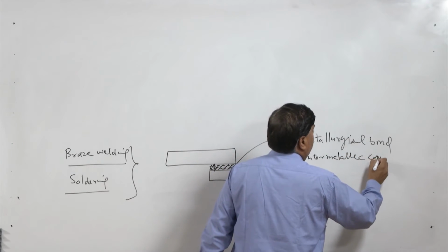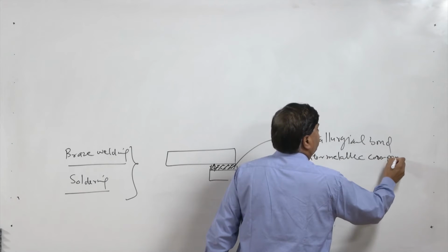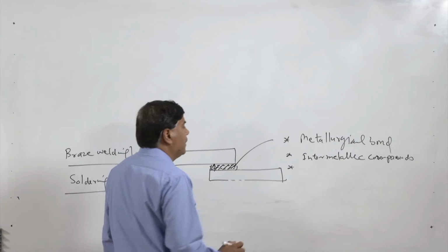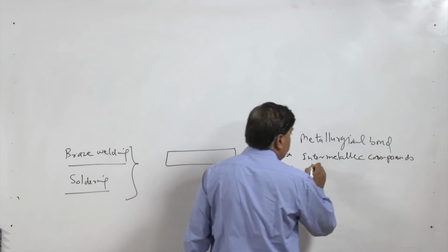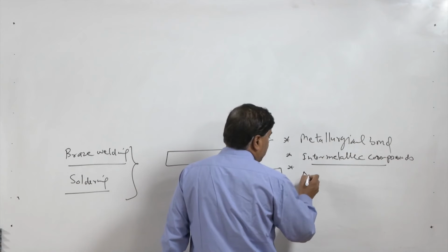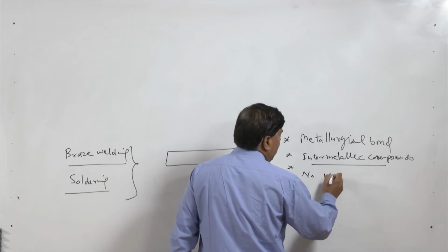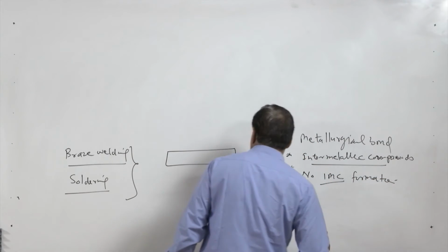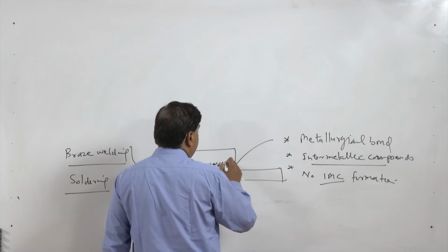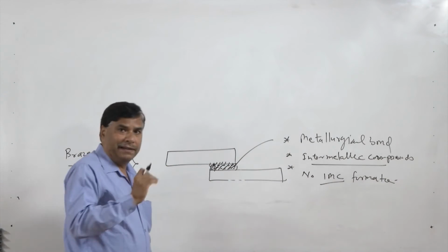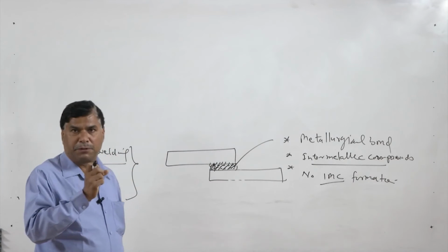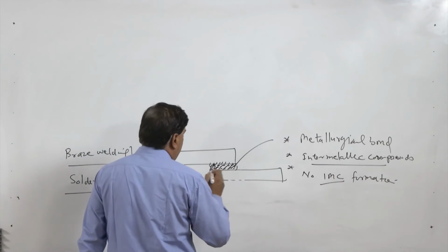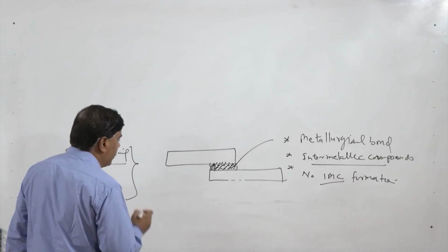between the sheets. If there is no intermetallic compound formation, then the strength of the joint is solely governed by adhesion, the way the solder metal interacts and closes the gaps at the surface of the workpiece or the sheets.